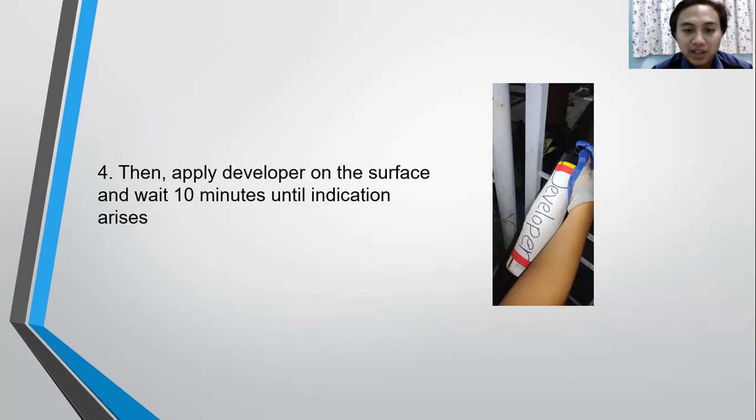The length of an indication can grow over time as penetrant bleeds out, causing an acceptable indication to become a rejectable defect. The length of the indication is measured for evaluation, not the length of the flaw. Here, for the result, as you can see, and the discussion and conclusion of our testing.